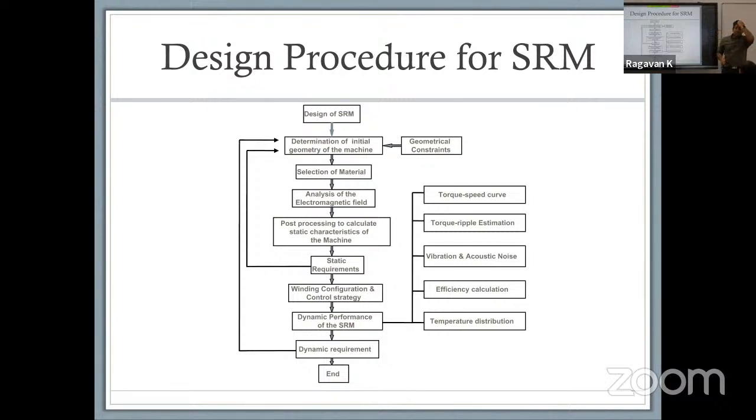Some of the mistakes that even we have made along the way was one of the times we did not take into consideration a standard housing. We assumed that because it was a brand new application, that we could select the stator size and machine out the housing. The challenge was the solution was expecting us to meet certain NEMA standards for the housing, and they wanted to have a pre-existing frame that they could use for the motor. So we ended up having to redesign the stator to a good extent because we did not take into consideration specific requirements that came from the application.